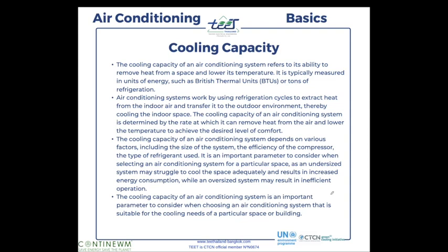Then they did another test at 23 degrees Celsius, so they decreased the temperature by 2 degrees, and decreasing by 2 degrees means you have more heat to remove. The air conditioning became too small in terms of capacity.